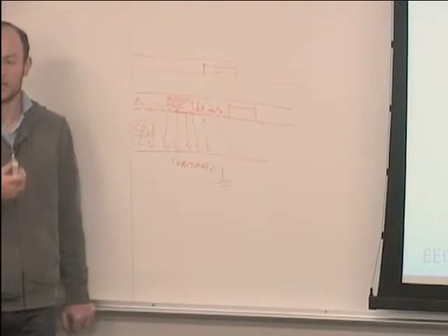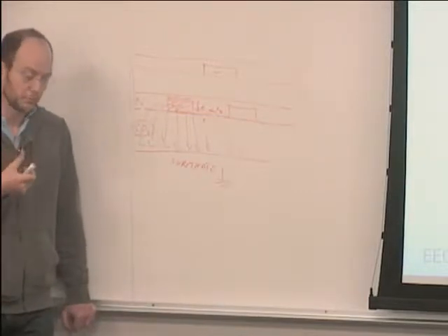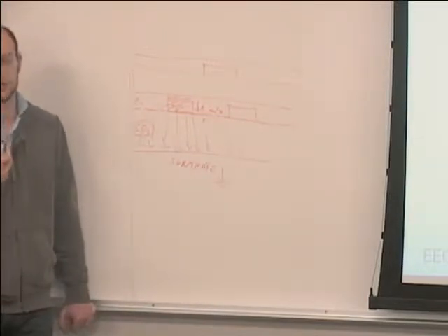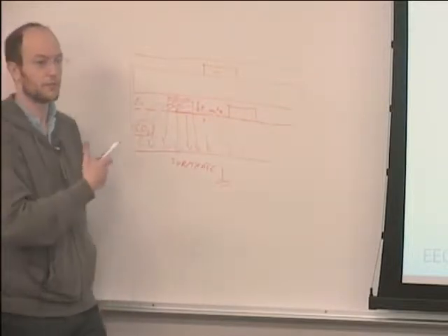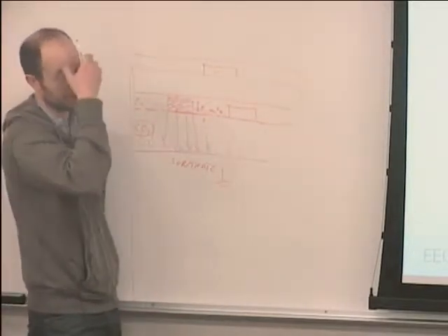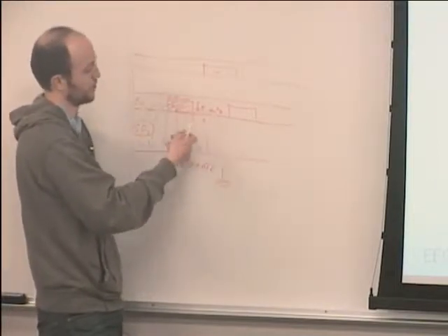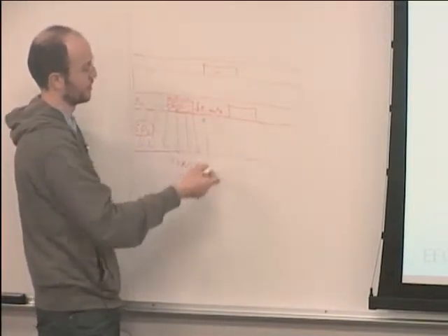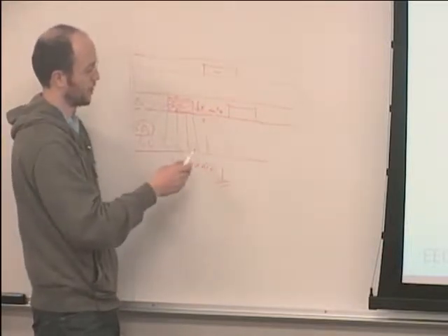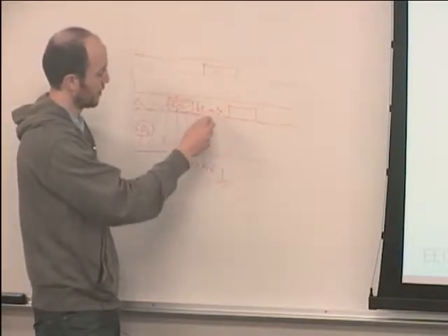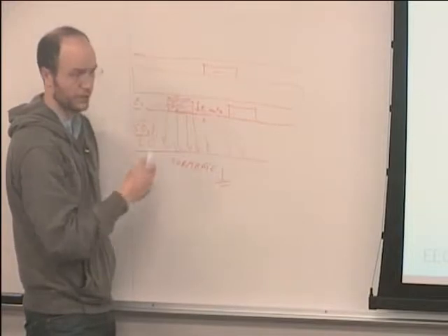width of the wire. So a wider wire has more capacitance, and it has also lower resistance. Okay? And typically the product is constant. To very first order, the product is constant. Then this fringing field makes it so that it changes a little bit with the width. Okay, so this is for one wire, all right?